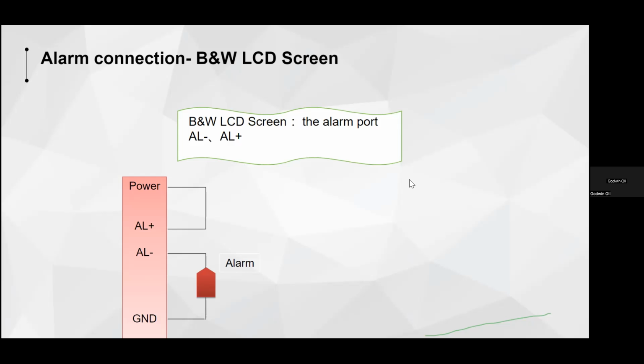The first question is far more important. Let's start with the most recent question you asked. What do you do? Because if it's not appearing, it means there is possibly a fault with your reader or a fault with the card. Because there's no way a device will successfully read a person and the person is not on the user's log, right? On the user's log, you see all the users that have been registered on that device. You see the ones you've given access right to use fingerprint, the ones you've given access right to use card. So if you're not seeing a card, you need to check.